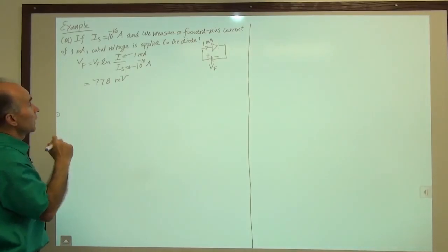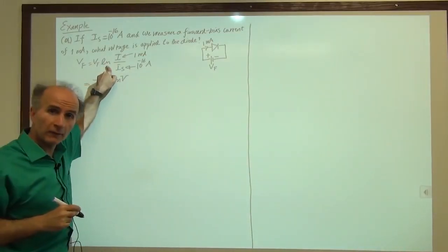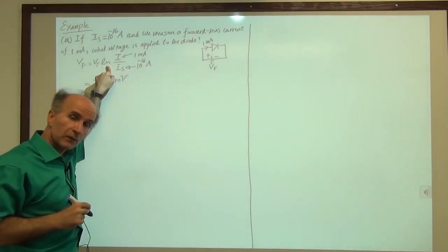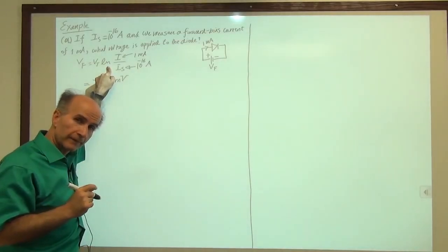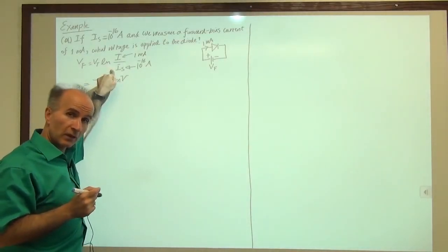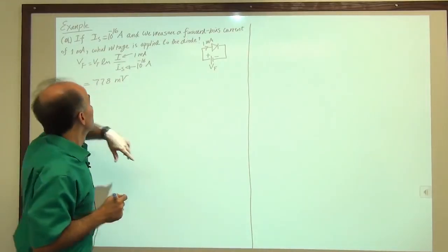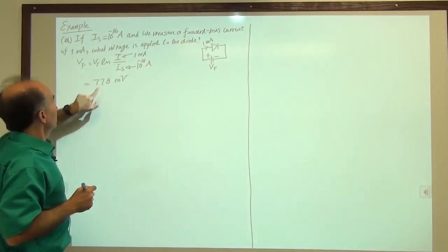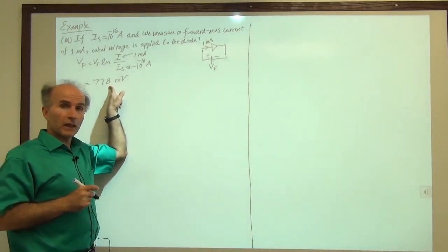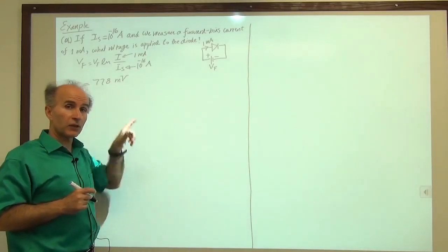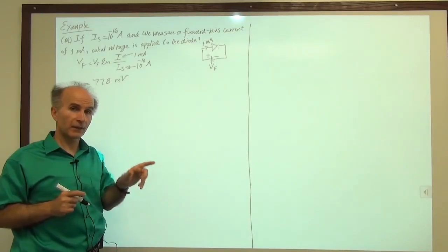okay, now one point that arises here is that in writing this equation for the bias voltage, I have assumed that that 1 is negligible with respect to the exponential. Is that a good approximation here? I just made that approximation and moved forward. I can double check and see. So we know that this is 778 millivolts. So if the voltage applied to the diode is 778 millivolts, how much is the current?